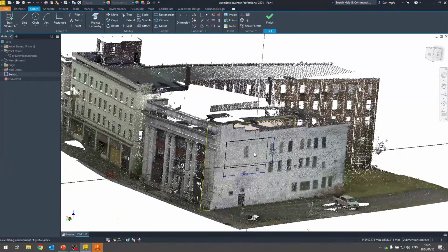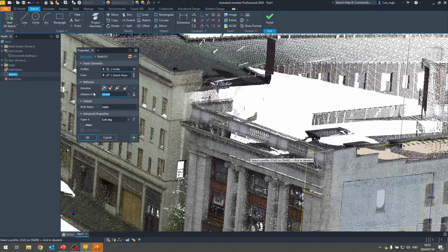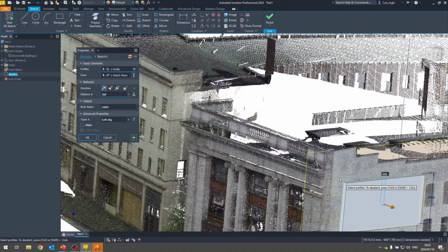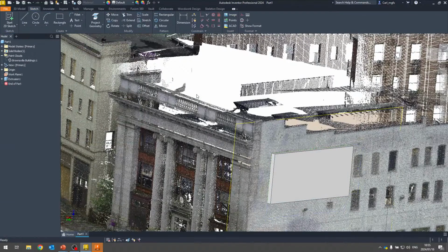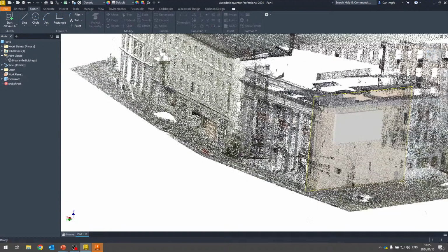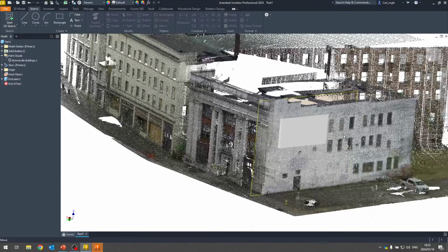I'm just going to do a very basic extrusion here on the side of this. Let's say that stands out. Maybe it's a frame structure that stands out half a meter to give that window a bit of clearance. And so you would go through your standard design process here now, but you have, in this case, the building in the background to be able to reference info. So we could create a sketch that represents the side elevation of the building.